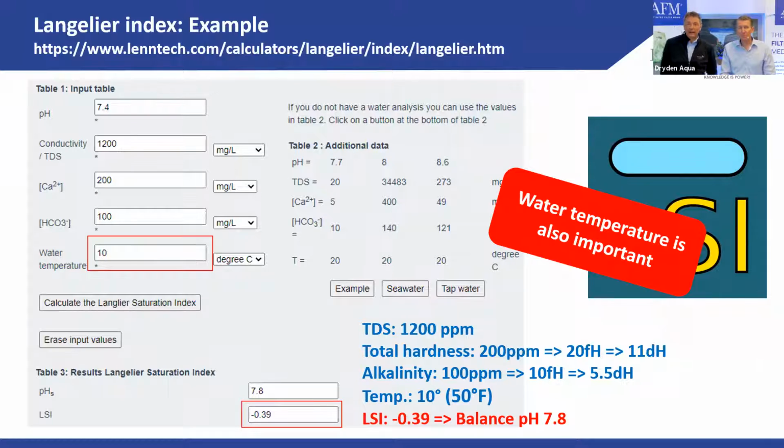It's usually alkalinity. And maybe this problem is not as big in the US, because a lot of our parts, skimmers, etc. are mostly stainless steel because they look better, or we have complete stainless steel pools. Now, I would not use these systems with a stainless steel pool unless you control the Langelier index very, very carefully. They are really expensive, and if they corrode, that gives big discussions about who is responsible.